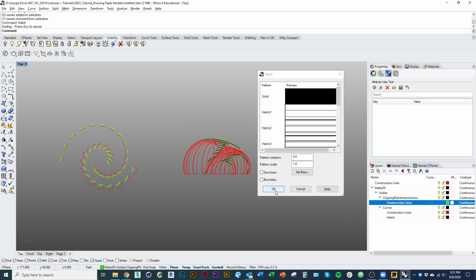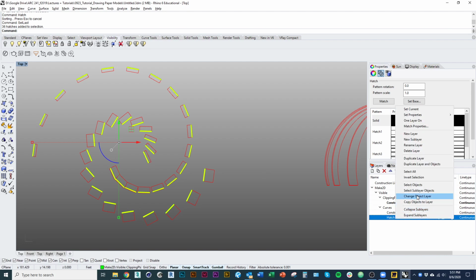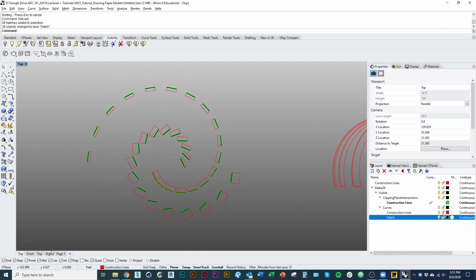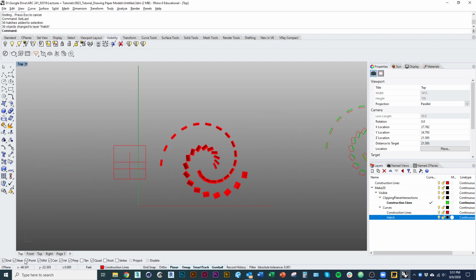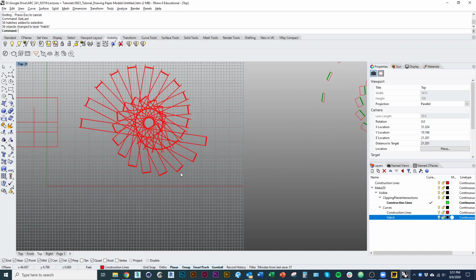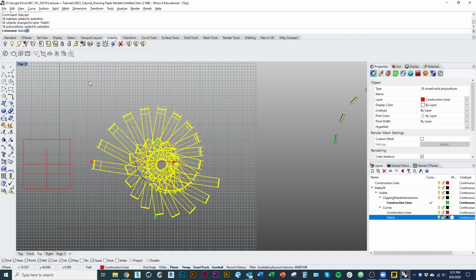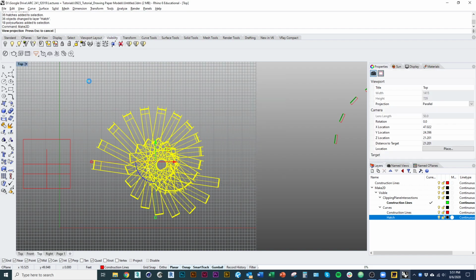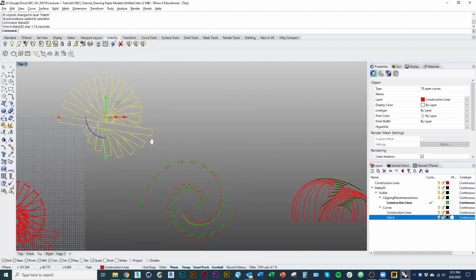Solid. Again, forgot to change my current layer first, so I'll just change that to my hatch layer. Okay, and then the other thing that might be useful, one of the things that you see a lot in floor plan is to show some information about what's above the plan cut. So in order to do that, I might go back to my top view here where I don't have my model clipped, and I could select my model and go make 2D. Okay, so now I have a separate drawing that I've produced independently.